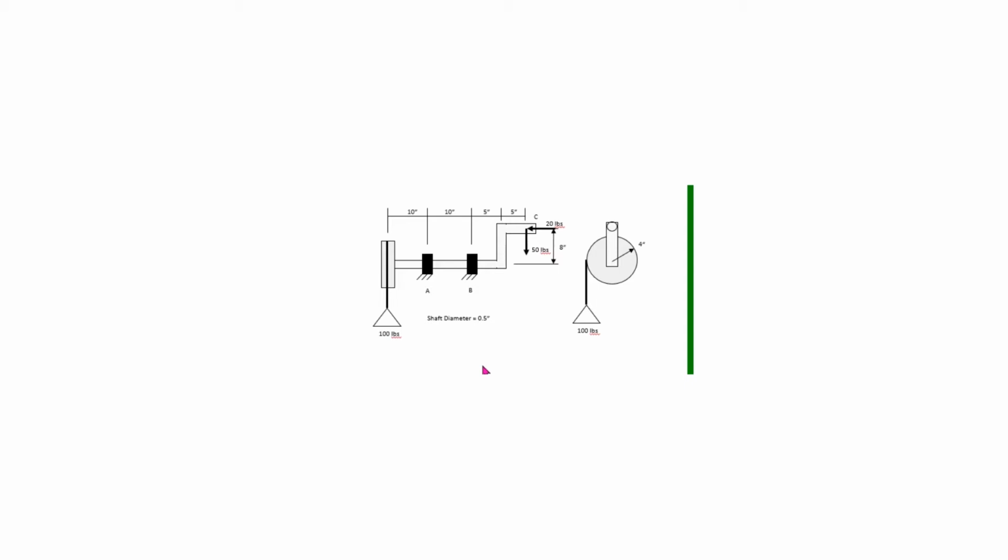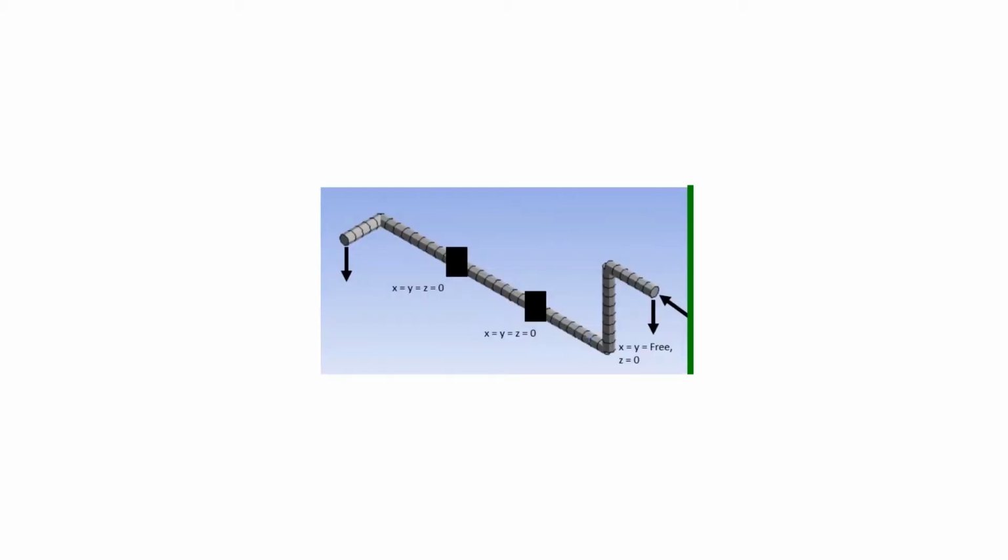Bearings can carry radial loads, and so these bearings will fix the displacement of the shaft in the transverse or radial direction. Bearing B will also carry an axial load. The focus of this model is to determine stresses and deflections in the shaft. We are not concerned with the end disc. Therefore, we can model the hand crank as a single continuous beam as shown. Here's the handle, the lever arm down to the main crankshaft, and then out to the applied load.